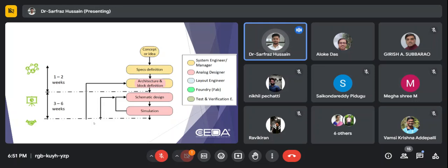Now when I explain the tool and all the usability, I guess it will be clearer. But of course, you can start with the DC-DC, but here we don't only focus on the simulation, we need to do the layout also, because finally the file that we need to generate is the GDS, since we are talking about the fabrication of analog IPs. So we need to generate a layout, a GDS2 file, and that GDS2 file we can generate using the Electric software.